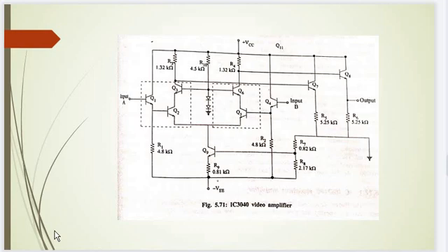The combined connection of Q1, Q2 and Q3 is in turn emitter coupled to the symmetrical configuration of Q4, Q5 and Q6 to form the differential input stage. The common collector stage formed by Q7 and Q8 provides the low impedance differential output for the circuit.